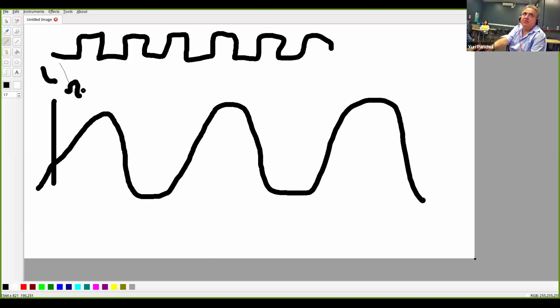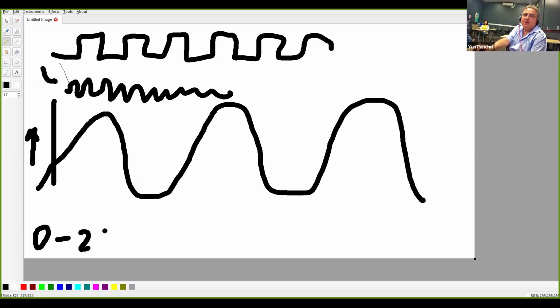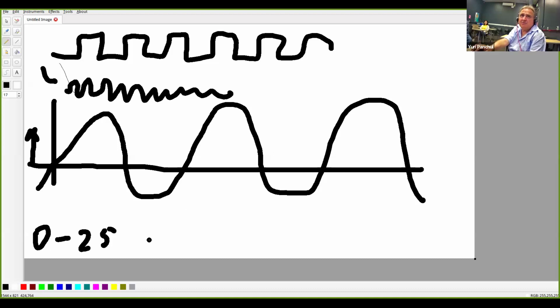We are getting this very frequent clock signal, and we are getting the current microphone level from 0 to 255 or some level. Actually it is a signed number from minus something to something. Now we are checking on a positive clock edge whether before it was negative and it became positive. This is the point where we start to count.